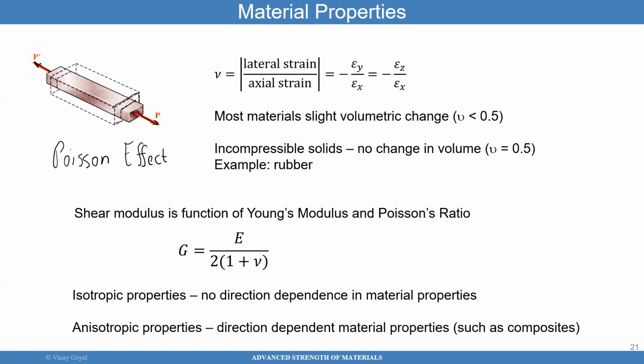So the Poisson ratio is really this: if I apply a load in the epsilon XX direction, then the Poisson ratio measures how much is contracting in the other direction, what fraction of that it is. So if the strain in that direction is epsilon XX, and I put a strain gauge going that way to measure that strain, the ratio of these two numbers gives me the Poisson ratio.